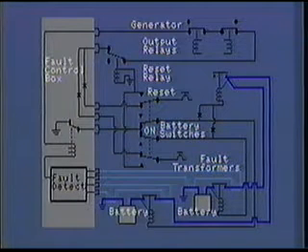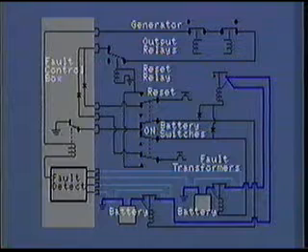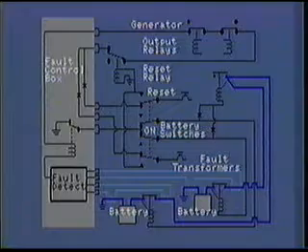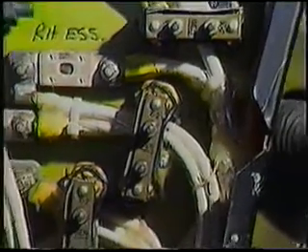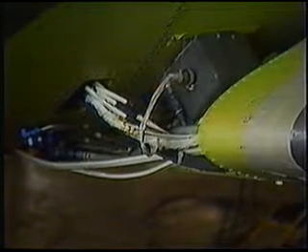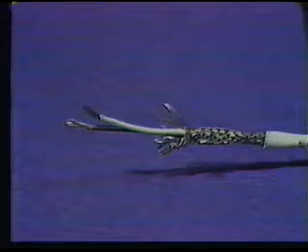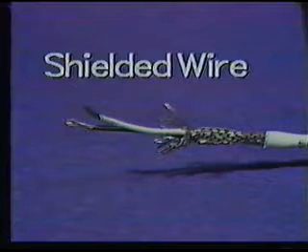The fault detection system works on the basis of equilibrium, a state wherein the fault detection transformers provide a variety of polarity opposite signals to the fault detection box. The signals produced by the transformers, although relatively small, are strong enough to accomplish the task. The trick is to get these signals from the X1 and X2 connectors unmolested through approximately 200 feet of wire to the fault box. For maximum protection, the conductor carrying the signals is a special conductor called shielded wire.